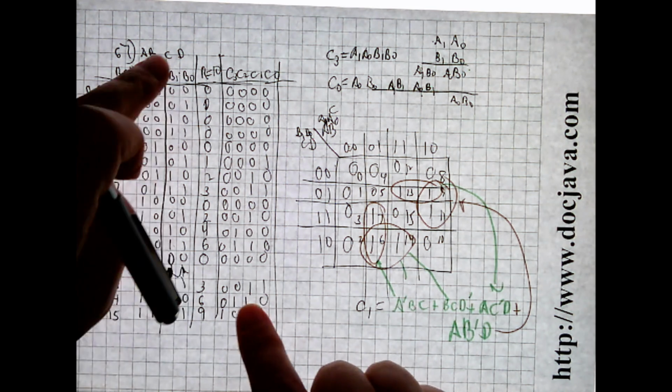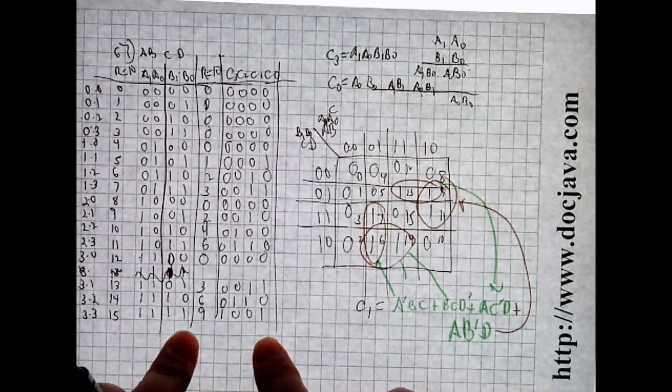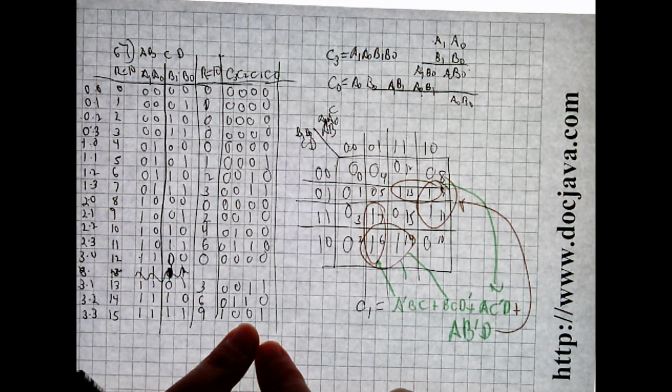And in fact, being able to do this exercise right in through here is a great way to find different ways to do implementations. And now that I think about it, you could probably do it with a decoder and a few OR gates, and that would be a way to do a multiplier very efficiently. But that's another approach to design. There's always more than one way to design something. So the answer for 67 is true, and I hope this wasn't too complicated for you, but there it is.